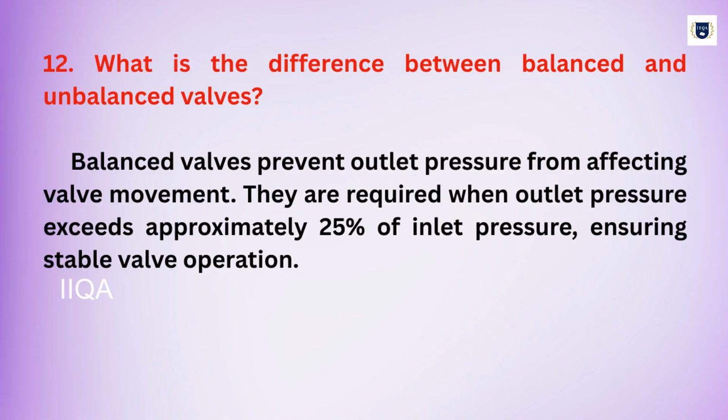What is the difference between balanced and unbalanced valves? Balanced valves prevent outlet pressure from affecting valve movement. They are required when outlet pressure exceeds approximately 25% of inlet pressure, ensuring stable valve operation.